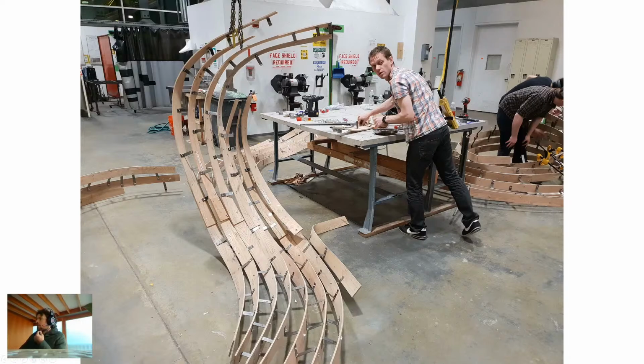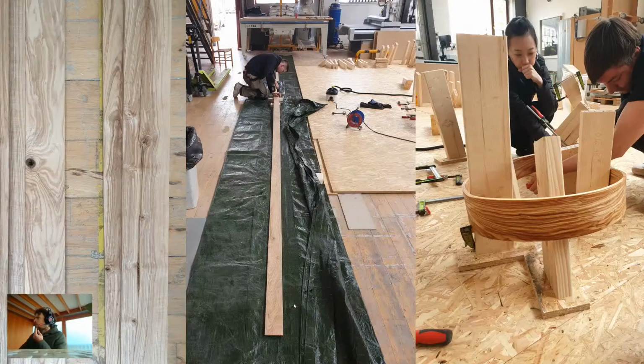And so we needed to start thinking differently about how we would design for this type of holographic construction. And what that effectively meant is designing really, really long parts. So in the first prototype, we used short parts. In the second prototype, we started using 12-meter long pieces of timber. And the reason for this was when you have a 12-meter long board of timber, even though it's sort of 15 millimeters thick, and you'll get some springback, the springback doesn't exceed the natural elasticity of the timber.